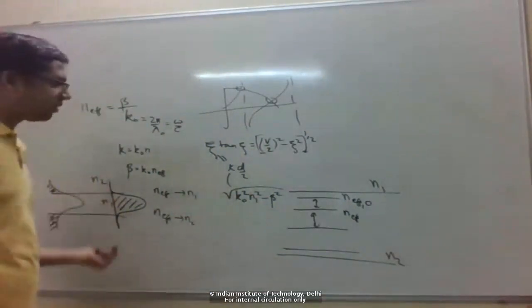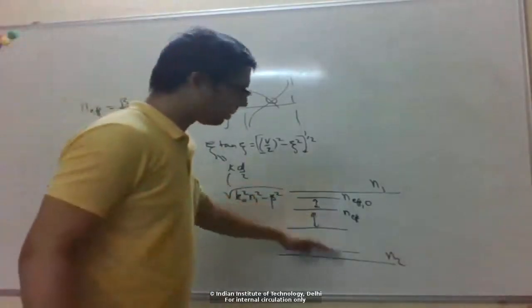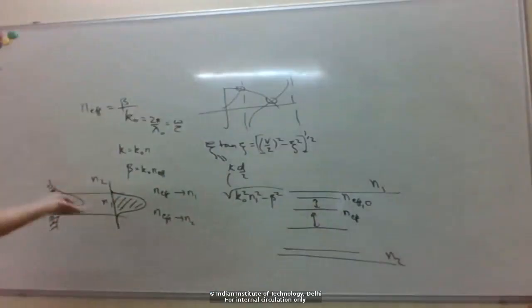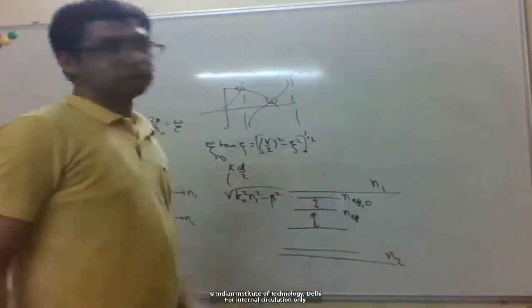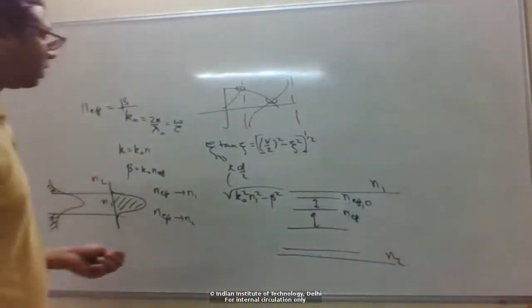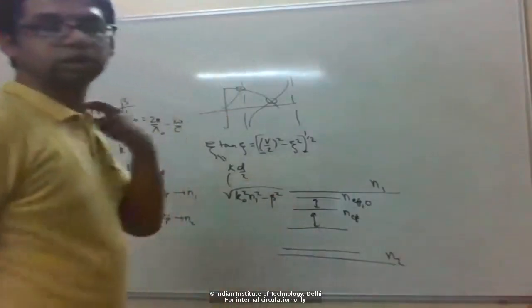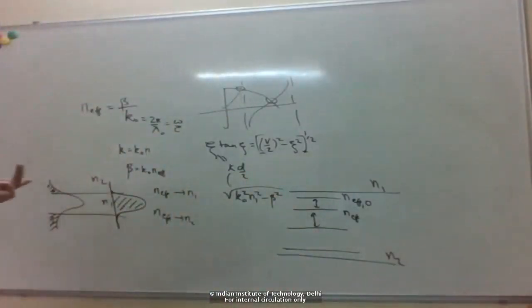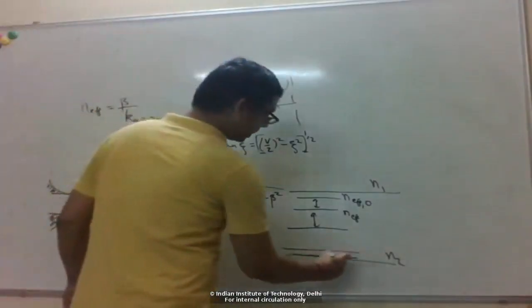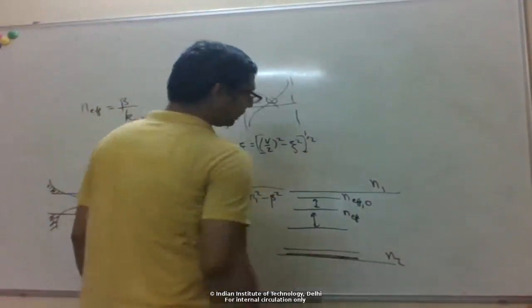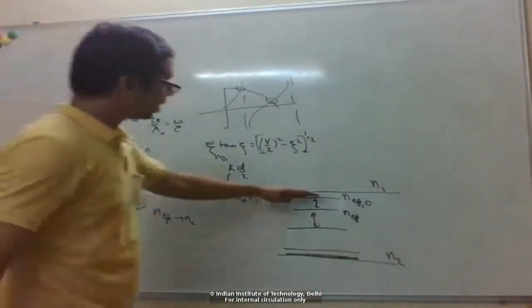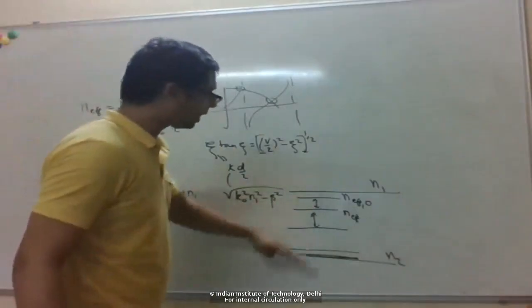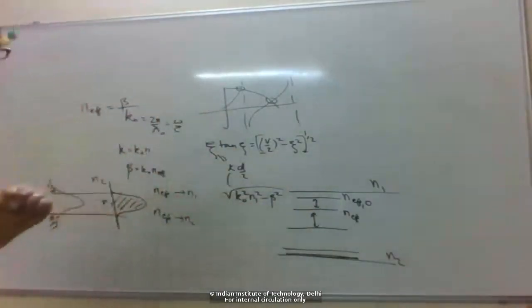So for different refractive index profiles, you will get different spectra of the effective index, but the general properties hold true. The well-guided modes, the lower order modes, have higher effective index, closer to n1. Higher order modes, which are less well guided, have index closer to n2. And the cutoff, as we saw, when this index becomes n2, is the mode cutoff. Beyond that, the mode is not guided. That's true for any waveguide. It's just that where the n effective values for the different modes occur depends on the particular refractive index profile.